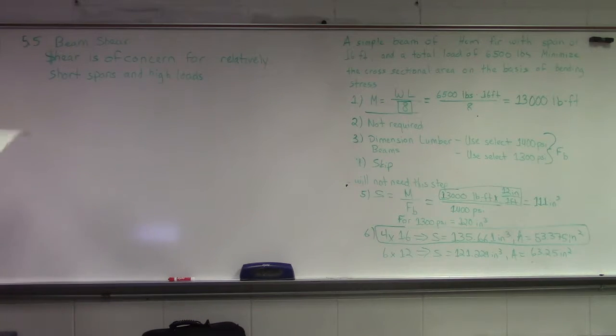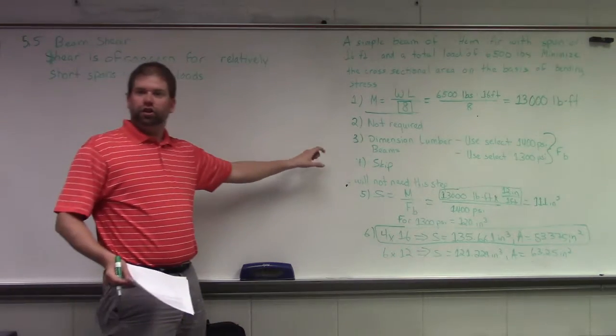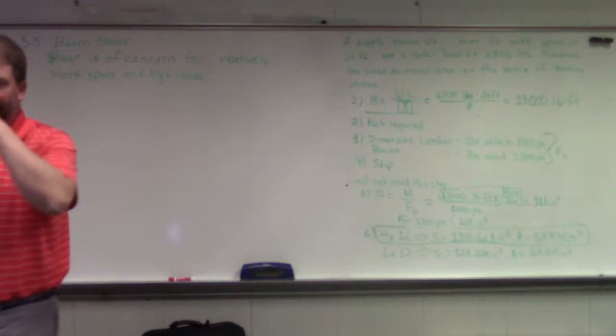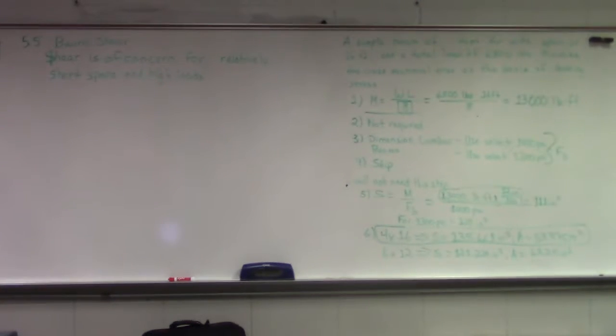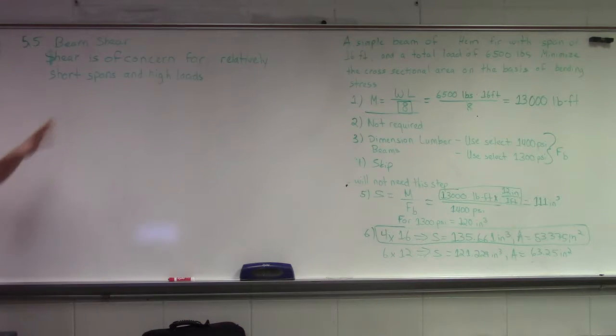Shear is typically of concern when we're talking about short spans with high loads. The reason it becomes a concern is our shear force will typically then take over from bending. Usually, when we're talking about structural wood, our bending is what's going to govern. But once we start getting into short spans and high loads, that's when shear is going to take over. There's only one equation you need to worry about.